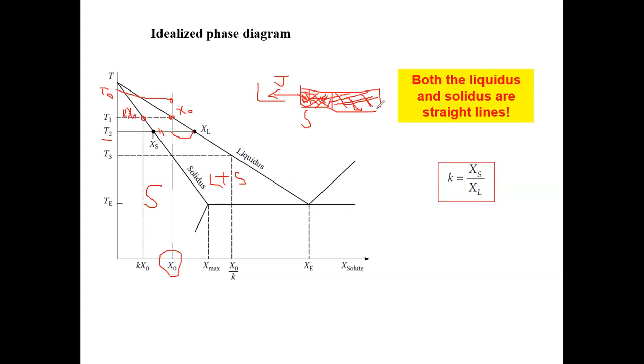Okay, so that's that. Again, we are going to revisit this concept back and forth. So it's totally fine if you still feel this is a little bit confusing at this stage. But the whole point is that if you want to impose equilibrium solidification in the alloy, you have to slowly, very slowly, but continuously lower the temperature.